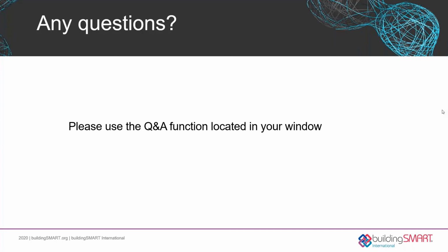Do you use any semantic dictionaries or standards to describe the digital twins within Bentley, things like the Building Smart Data Dictionary or eClass? Do you integrate with those standards? The way we align and bring cohesiveness to all of that data is through something called a BIS schema, the base infrastructure schema, that other schemas are built on top of, whether it's construction, building, or others.